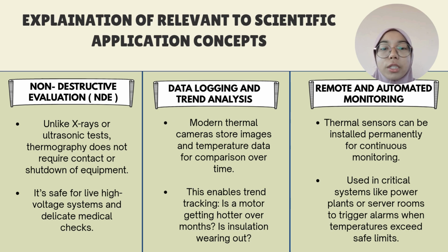The second application of the thermography concept is data logging and trend analysis. Modern thermal cameras store images and temperature data for comparison over time. This concept enables trend tracking. For example, is a motor getting hotter over a month? Or is insulation wearing out?